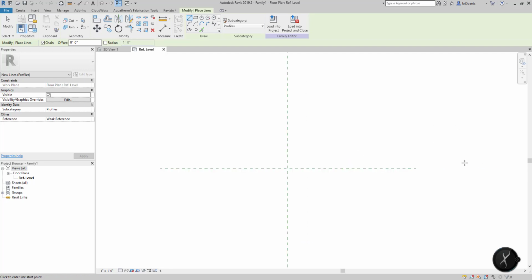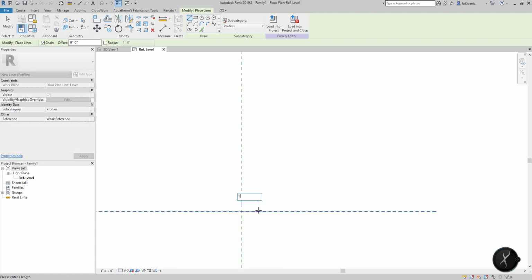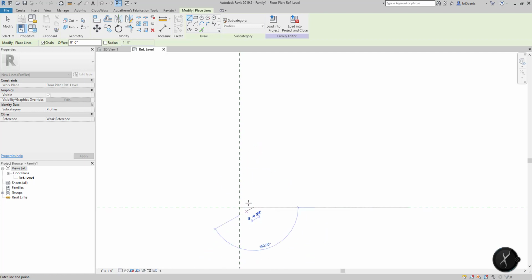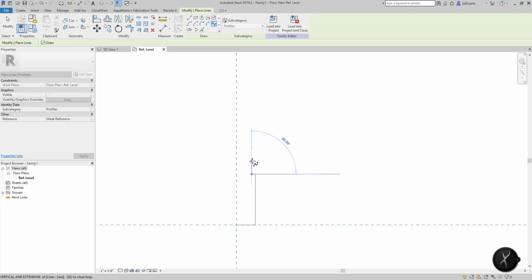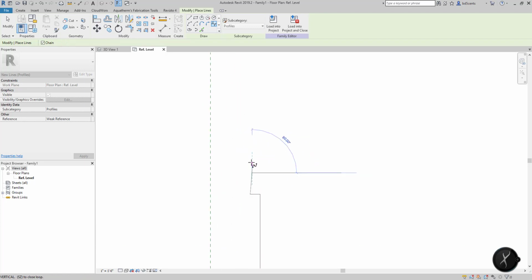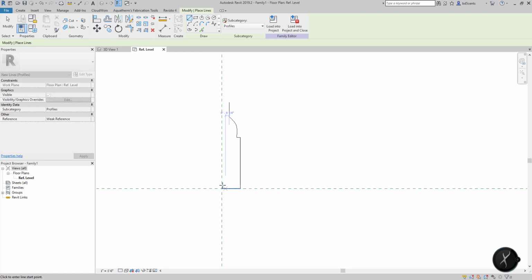So what we're going to do is go in and draw out a base crown molding profile. So we're going to go 1.25 inches. And we're going to draw up ballparked about halfway, so about 3.5. And we'll go out about 1/4 inch, and then we'll kind of spline our way up into creating kind of a rounded profile edge. And then we'll draw this up just a hair here. And we want to make sure that the overall is about 5 inches.